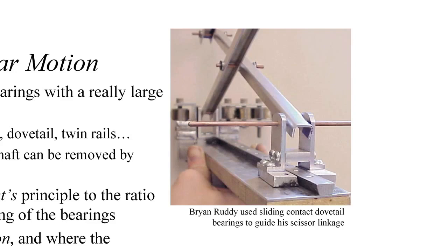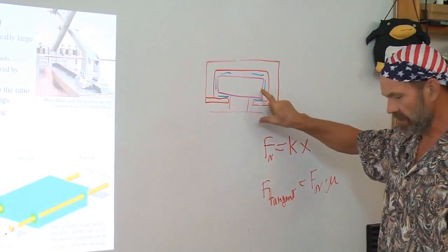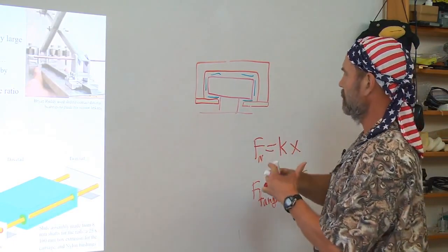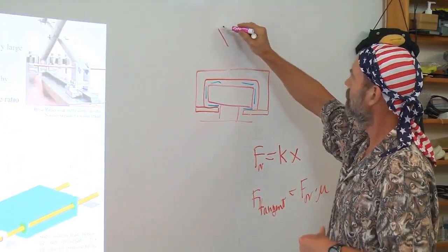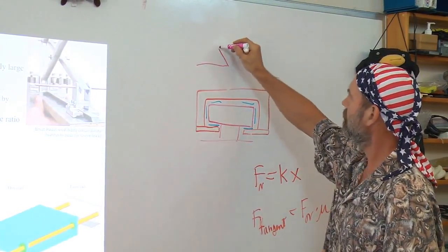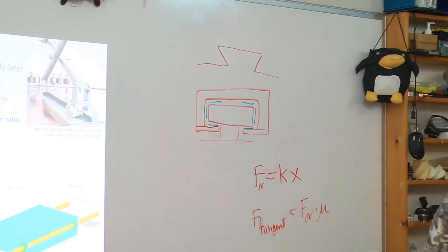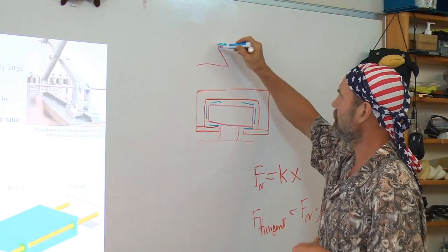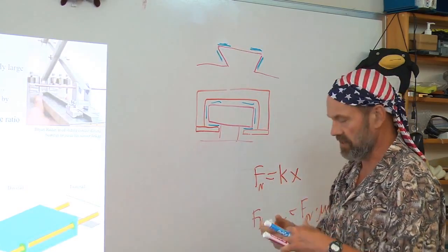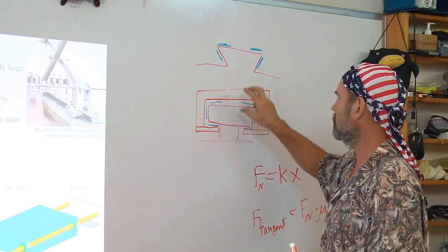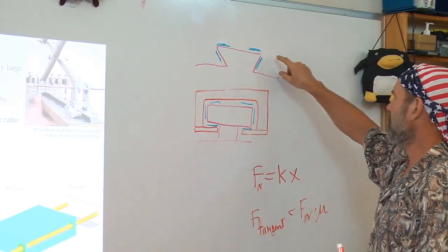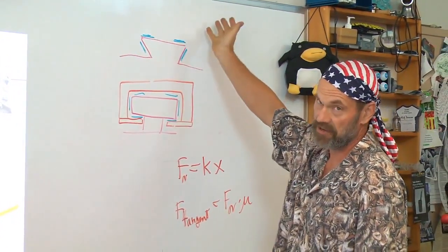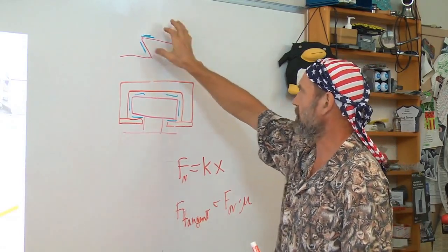This dovetail shape compared to this boxway shape, notice that for this carriage, I'm now going to have this type of bearing arrangement. And when I say a bearing pad, it's implicit in here that this is a separate, like a plastic element, but it doesn't have to be. It could be, for example, cast iron, and then there's either a steel carriage running on it, or it could be cast iron if it's well lubricated, or you could have plastic pads on it.